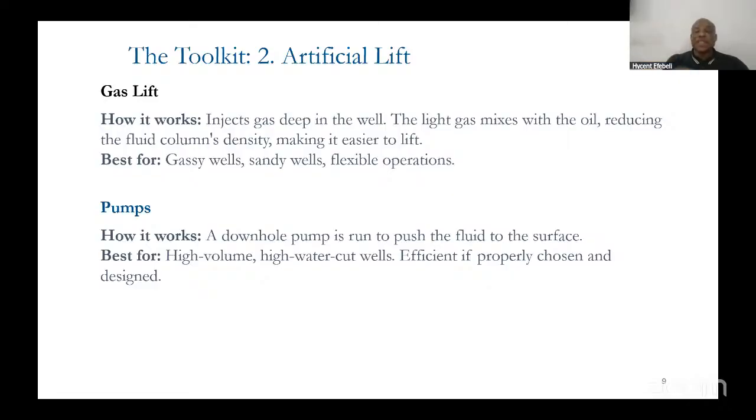Yeah, so the other things, just like we've discussed, you are looking at gas lift. Some wells initially may not need a gas lift, right? Because maybe the GOR is high and the viscosity is low, right? But as you start producing more water, like I said, the average density of your fluid stream becomes too heavy for your natural energy from the reservoir to lift.